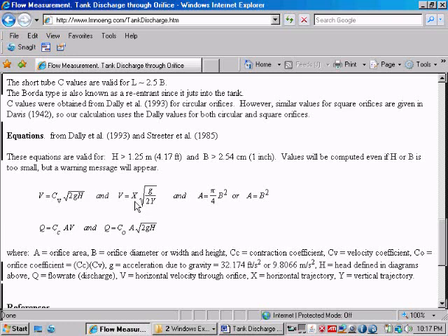So at our distance of 12.75 inches in the x direction and 9.25 inches in the y direction, the velocity at that position can be computed. This g is the acceleration of gravity, 32.2 or 32.174 is what our calculation uses, feet per second squared, and then x and y would need also to be in feet in order to compute the velocity in feet per second.